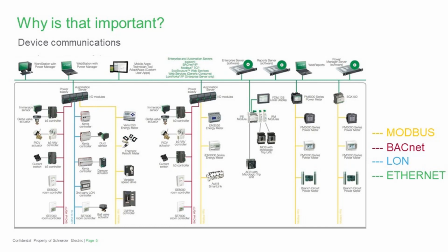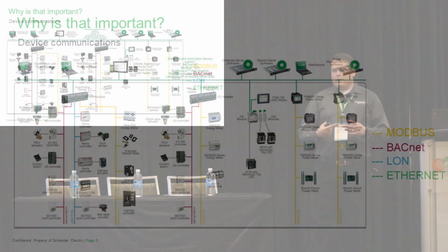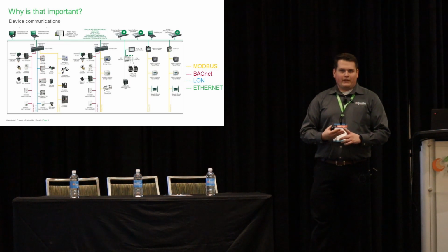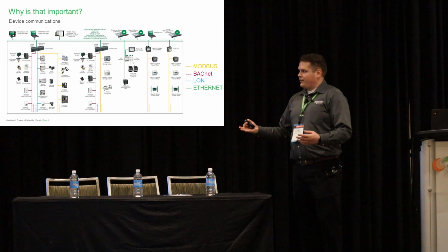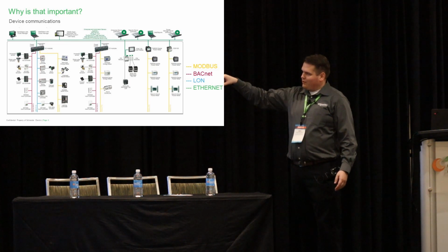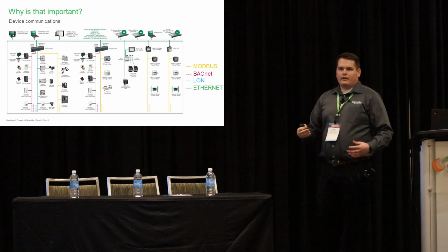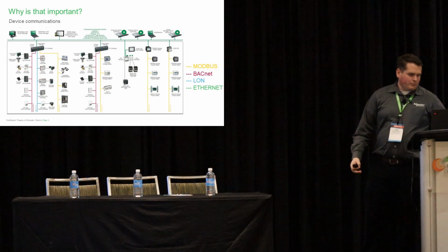You have to translate that data from one language to another. It's like a language translator if you go to a foreign country. Getting that data together is the key part. So, like I said in the beginning, each manufacturer kind of has their protocol. Modbus was developed by Schneider Electric. Allen Bradley was Ethernet IP. Siemens was PROFINET, PROFIBUS. So bringing all that together is the key. You can see at the top level, there's devices that are converting all those protocols so they talk together and keep all that data going back and forth pretty well.